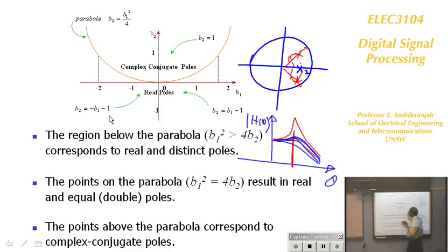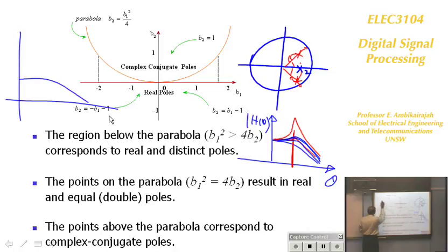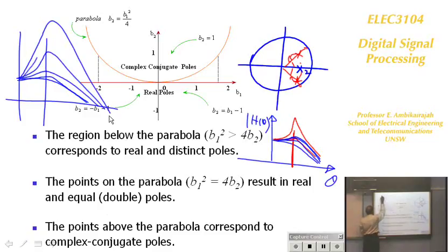But if you want me to draw a bit more detail, this is what you get: a low pass filter like that with a real pole, and you just fix the resonance frequency. There it goes, has a little bump, then a little more, and a bit more, and then sharper, and then very sharp. So this is R equal to 0.9. You're moving, and this could be complex.